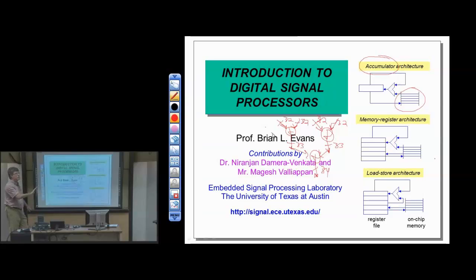Now this is about without loss of precision. I can certainly add all I want and throw out bits, right? So I have an option on the processor in lab. I can add 2 32-bit numbers and keep the result in 32 bits. Or I can use the long 40-bit word and keep the full precision.